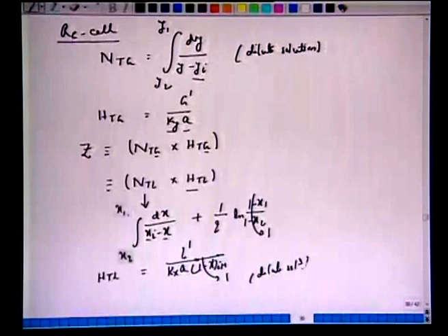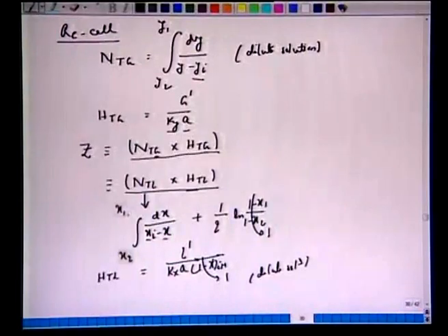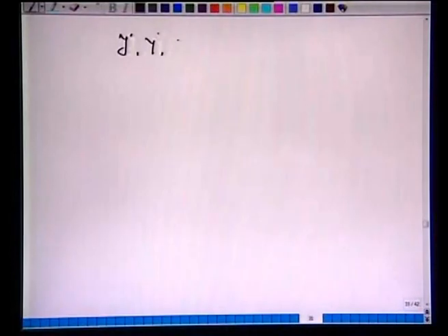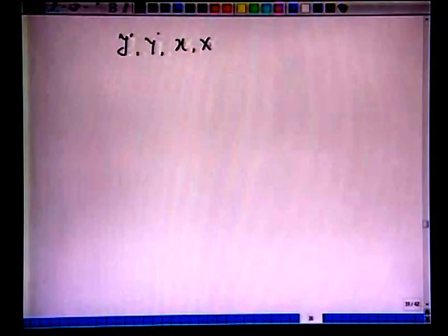So, in both ways, whether you work on the gas phase or on the liquid phase, we should be able to obtain the same results for the total height of the column. One can also define NTG and HTG based on bulk concentrations, that is Y star or capital Y star, or X or capital X star. All right. So, based on these bulk quantities, one can also obtain the number of transfer units and the height of a transfer unit. So, if you recall, we have the interface and then the concentration drops, right.